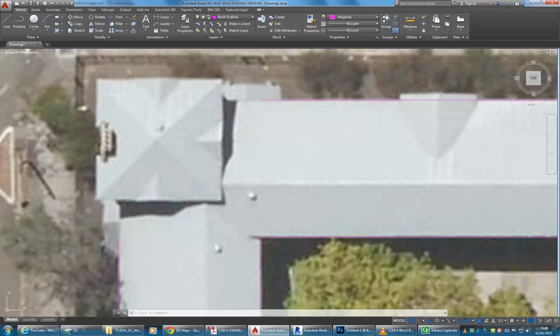But the survey only has the outline of the building, and you shouldn't rely on that. You should only use the survey for the site measurements and levels. So yeah, you measure and work out everything yourself for the building. Yeah. It's a really good thing to practice. We used to start in first year. That's how we used to start every project. But now,